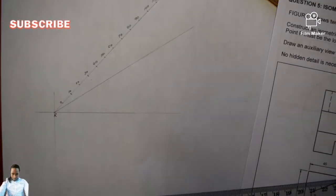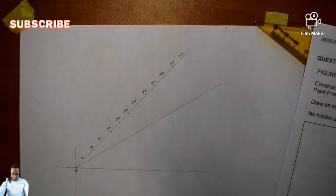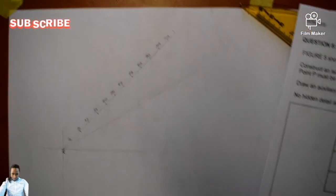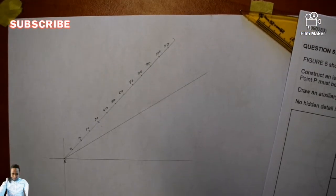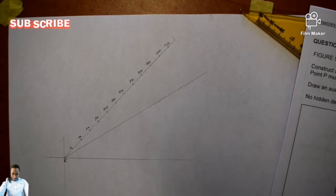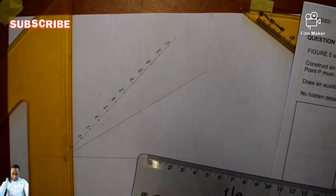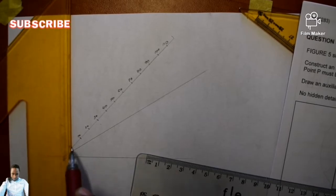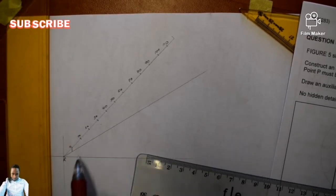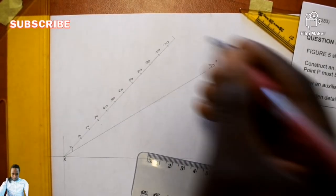After you've gotten your isometric scale up until 110, even if you end at 100, it's still fine. What is going to happen now? I am going to project point 0 vertically down toward the line of 30 degrees.